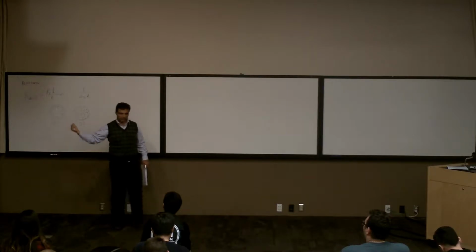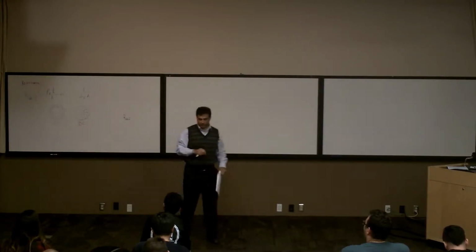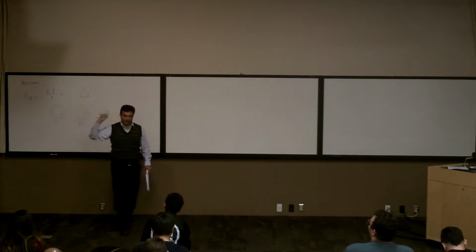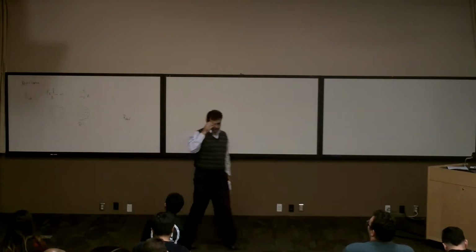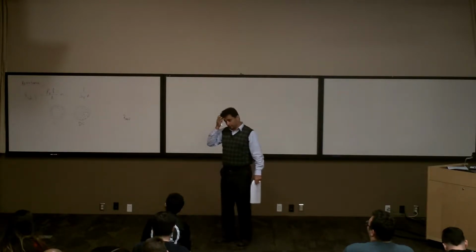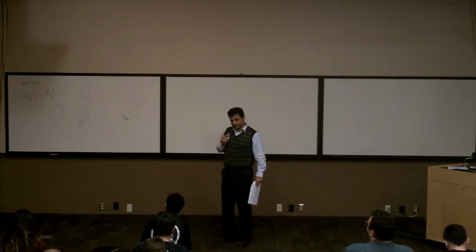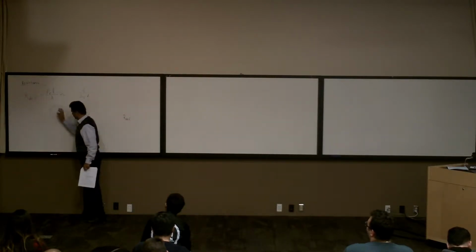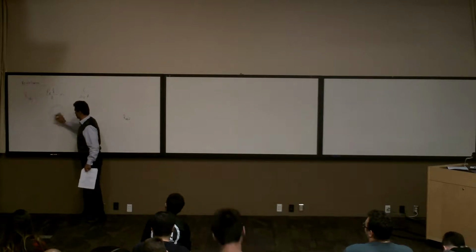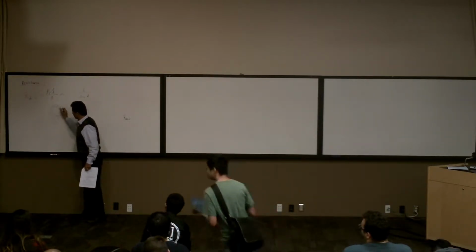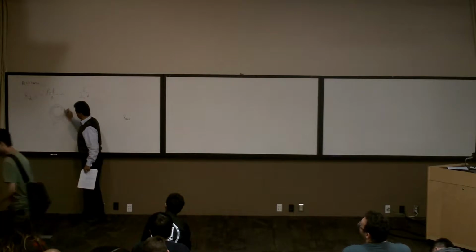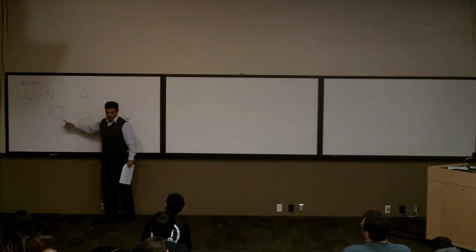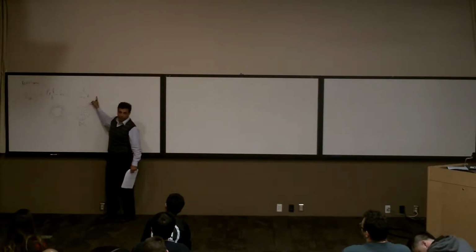So what's the result of this? Can you tell me? Let's say this is the same conductor, and we pass AC current and we pass DC current. Less net current. Why higher resistance to the AC? Less surface area. If you look at it here, let's assume there is no current in the middle. There is some, but let's assume the effective area for AC is this area, whereas here we are using all the area. In this one, the area is smaller, right?